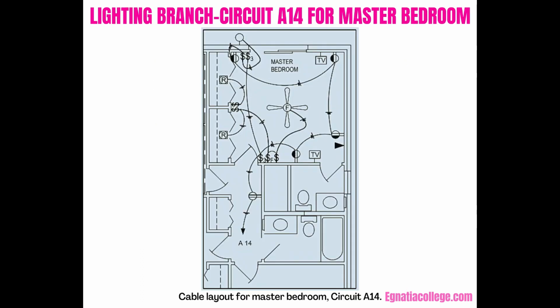in these runs and to economically select the correct size of wall boxes. This figure and Table 11.2 show a sample device and wiring layout in which circuit A14 has 4 split-switched receptacle outlets in the bedroom, 1 receptacle in the hall, 1 outdoor weatherproof light, 2 recessed closet fixtures each on a separate switch, 1 paddle fan/light fixture. In addition, an outdoor GFCI weatherproof receptacle is located adjacent to the sliding door and is connected to circuit A24, which also includes the other outdoor receptacles.